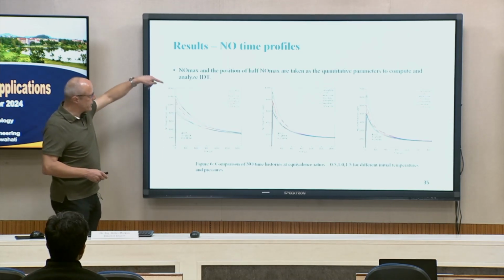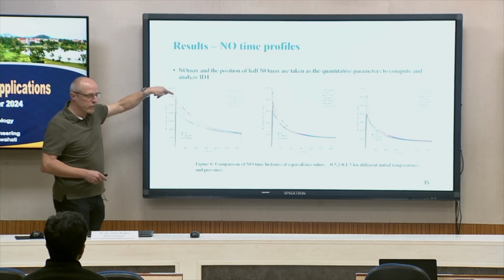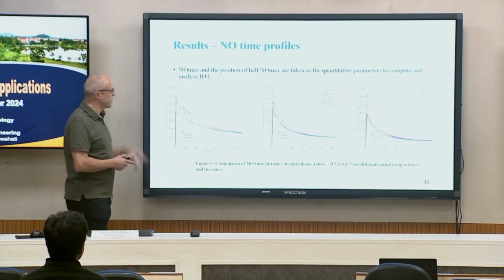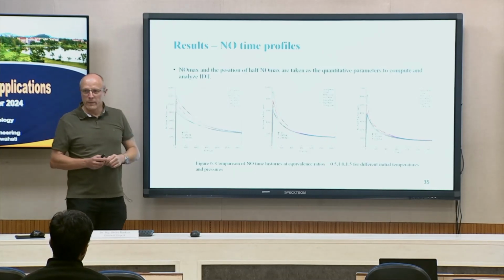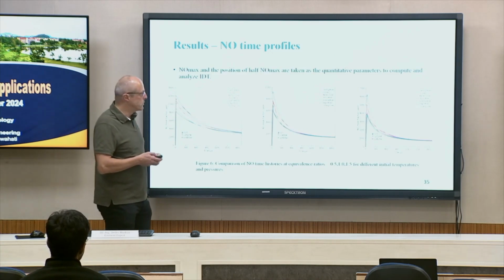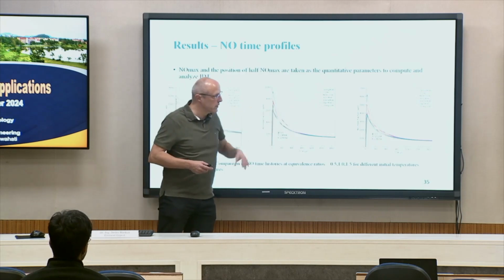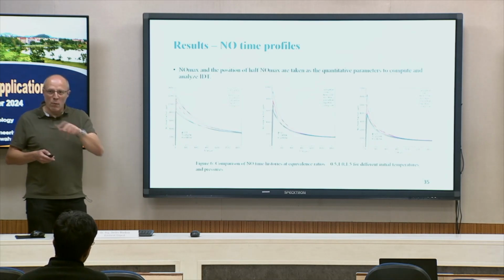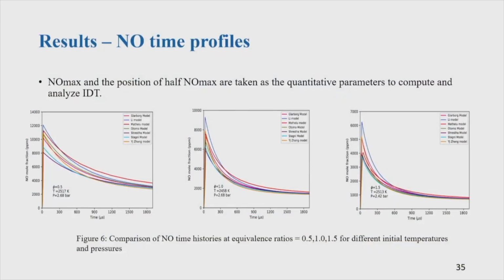But what you, for example, can see is here we have a lean mixture, phi equal 1, stoichiometric mixture, rich mixture. And what is interesting to see, the amount of NO reduces. And this is something, of course, we have expected. So if you have slightly rich mixtures, you get the minimum of NOx formation. Therefore, this is something we could expect, but we have to check, is the outcome we see here consistent with the literature, or have we done some errors?